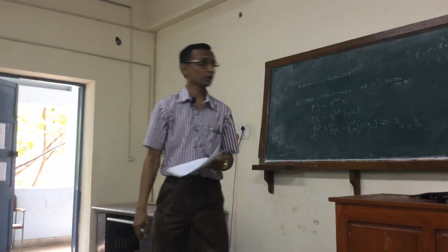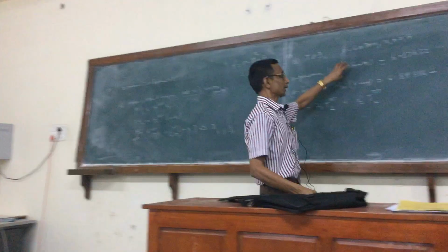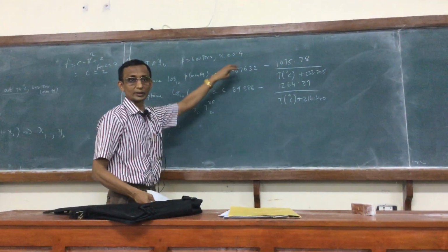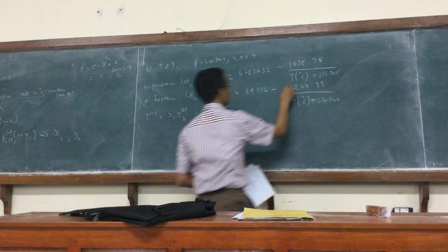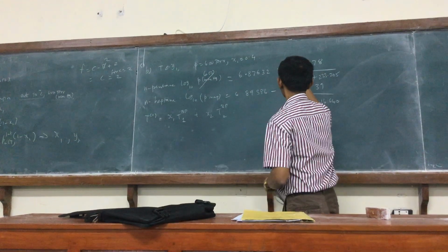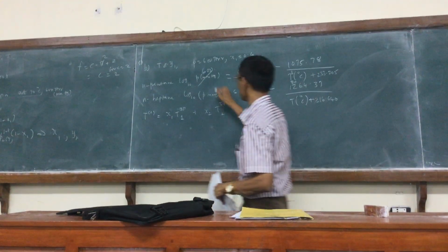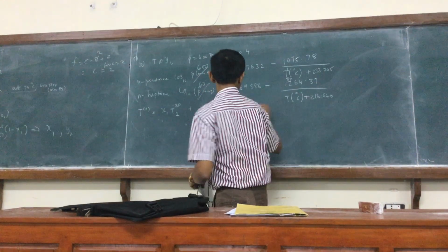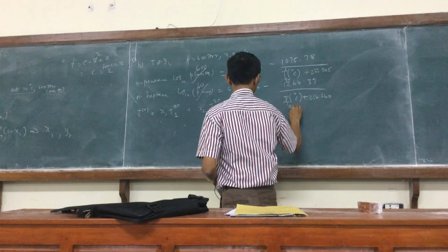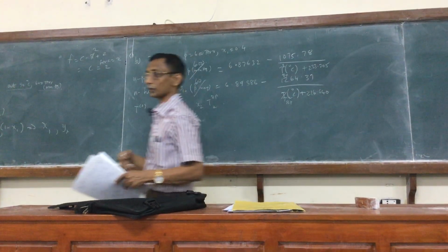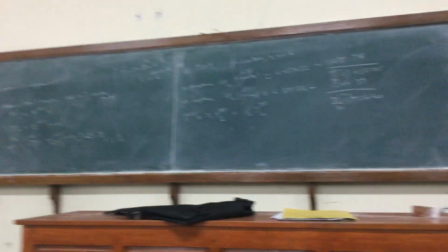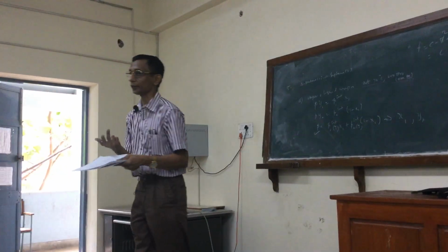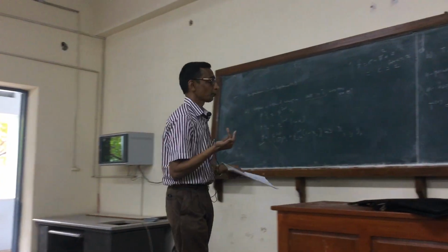From the Antoine equation. This is typically used to calculate the saturation pressure given the temperature, but if I substitute 600, I will get TB1. The Antoine equation can also be used to get the pure component boiling points given the pressure. Given the temperature, you calculate the saturation pressure.